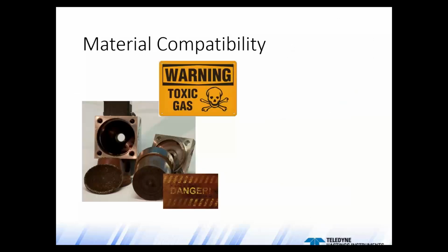Of course, we want to ensure that the process gas being used does not have any issues with compatibility. If there are elastomeric seals in the flow device, we want to select the right material. Maybe it's Viton, neoprene, Buna-N, Kalrez. We want to select the right seals that will work with the process gas. And it's not just O-rings that we need to consider. We may also find that we have other material issues that should be addressed when configuring the mass flow controllers.